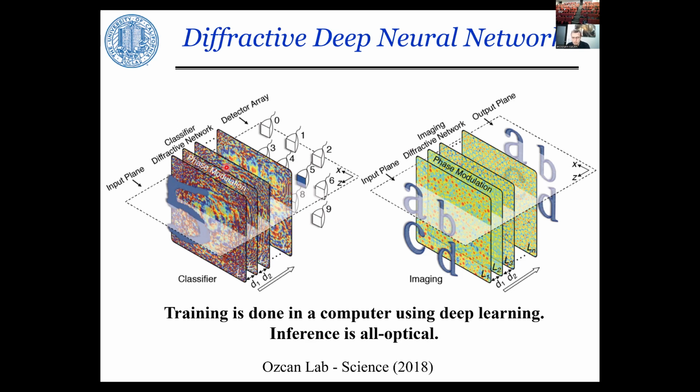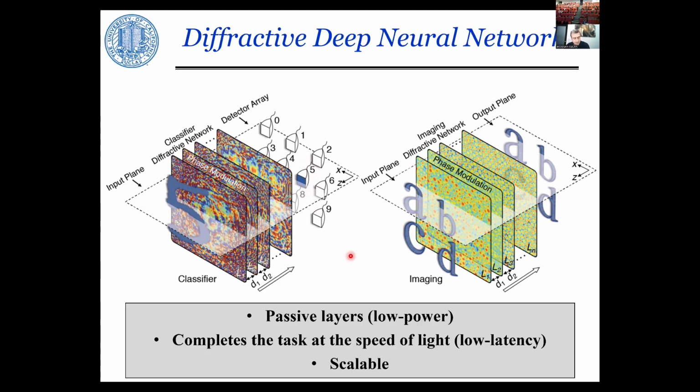For example, you can design a diffractive processor, diffractive network that can classify objects in front of it by routing the photons to a predetermined detector that is assigned to a class. Rather than creating an imaging system and classifying the object, you can actually have new objects here, never seen before, that can be classified based on the maximum number of photons that the diffractive system routes to the back focal plane.